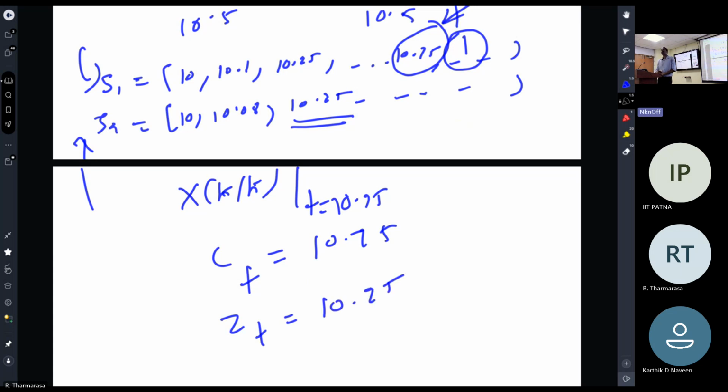So the Kalman filter cannot handle that problem because the time difference is negative. Right? So even though there are no real out-of-sequence measurements, the way we do the sequential update, it just introduces out-of-sequence. In this case, if you throw away this measurement, then you won't use sensor 2 at all. Radar 2 measurements, you are throwing away all the time. So at that point, you have to handle the out-of-sequence if you want to use it. If you are real world people using a rotating radar, this problem is always going to be there.